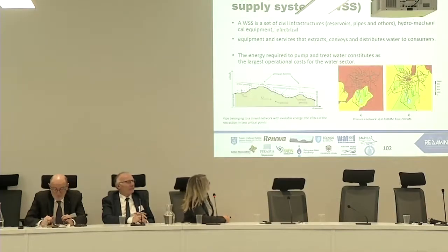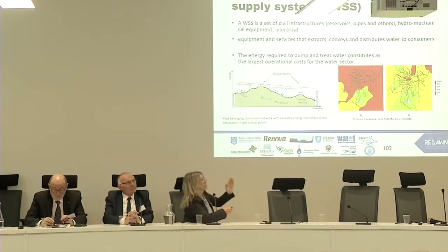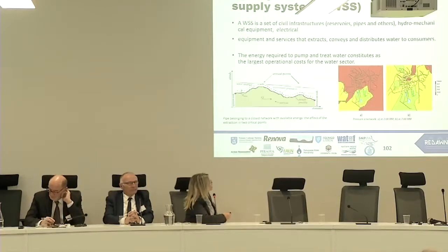Well, we can apply hydropower schemes in water supply systems. We are talking about this. It's important to see the critical points in order to preserve the minimum pressure in all the system. We need to guarantee a minimum pressure in all the system when we have the pipe along the ground. It is important to analyze along different hours because we have consumption of water which varies along the day. It's very important, and it implies different pressure along the day.